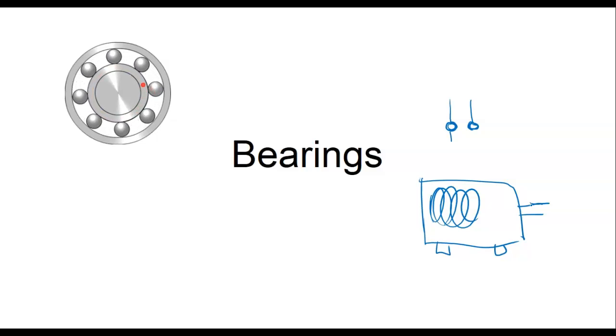So you've got your drive shaft, you've got your rear axle out there, and you've got to take it from your differential in the back and run it through a tube out, and it's stationary, right? You understand? It's stationary, and then your rear wheels are spinning. So you're going from something that's spinning and connecting it to something that's stationary, and this is where your bearings come into play.